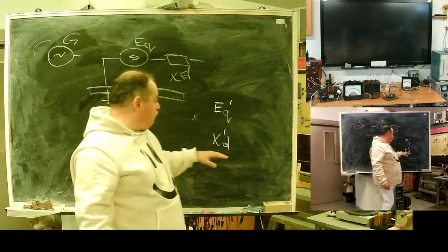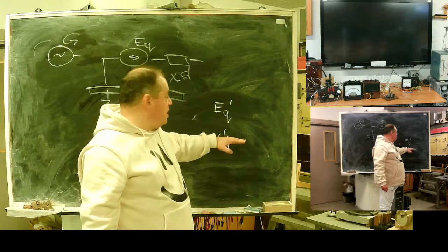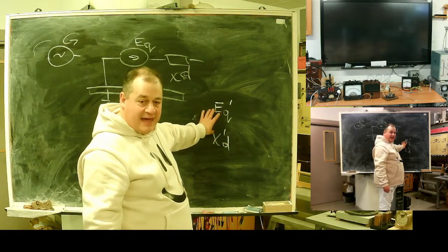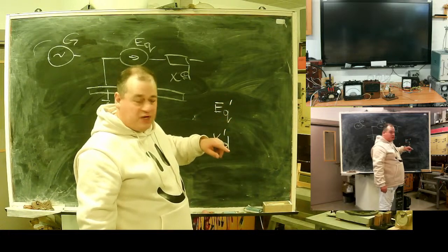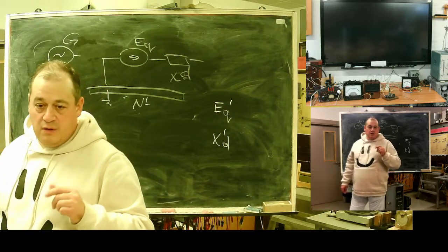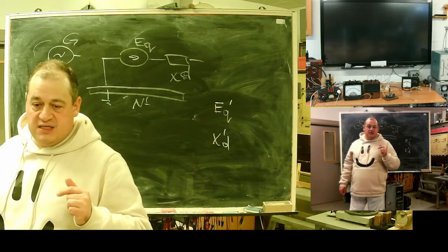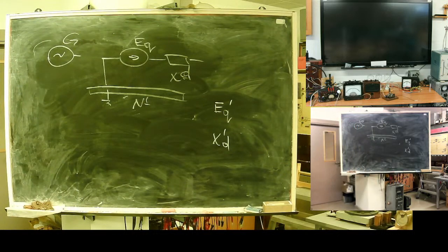If you have a fault in proximity of your machine, take a look into the machine data. Manufacturers supply transient EMF and transient reactance. That's not all.